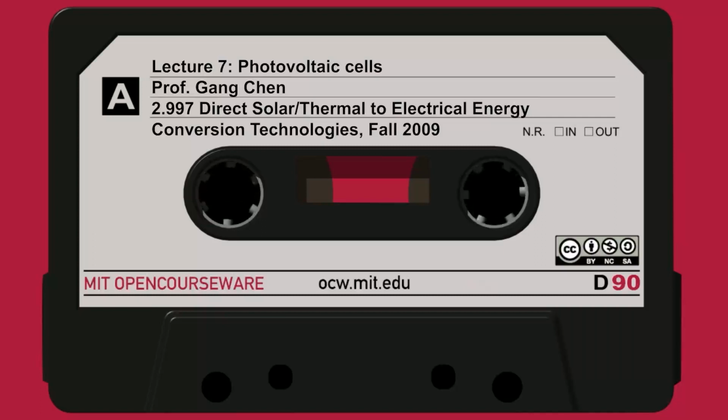Okay, starting from there, the rest is simple, just math. I can say what's my open circuit voltage, and my open circuit voltage is just to say there's 0 current. So if I set this side equal to 0, I find the open circuit voltage.